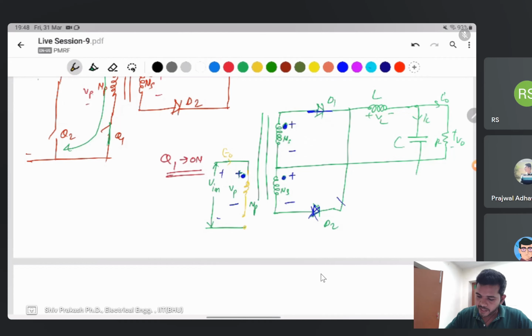That's why the remaining current, the discharging current of the output inductor, goes to both sides, through D1 and D2, not only D1, because the voltage is 0 on the input side. It behaves like an impedance only, and because both windings have the same impedance and the same turns, the current flows like that. Both diodes are on and discharge through them.